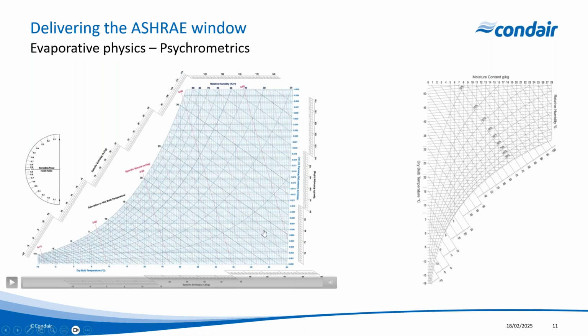Now, from two of these parameters, we can actually derive several others. So if you have a dry bulb and, say, a wet bulb or a relative humidity or the moisture content, you can actually derive the specific enthalpy, which is shown on the sides of the chart here, going diagonally along the left side and then along the bottom here as well.